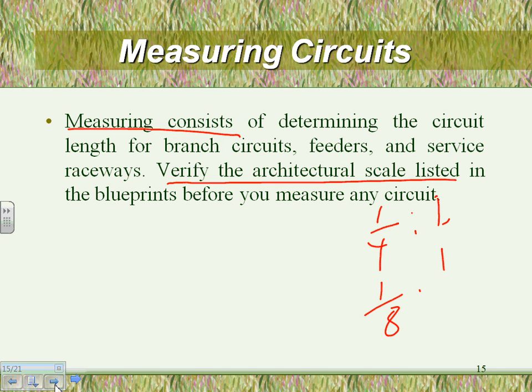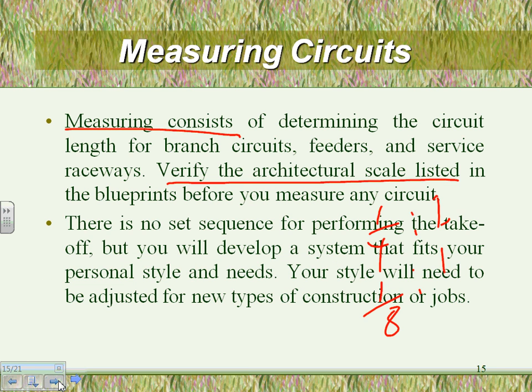A door, like a 3-foot door, or a window, sometimes they have dimensions and certain things to scale. You measure it: it says 4 feet in this direction, and you go measure it. Yeah, it says 4 feet, so the scale is correct. Because a lot of engineers have scale stuff. Sometimes they give you a half scale copy of it, and that will screw up your measurement, especially for distances. For the counts, no problem, but the problem is for distances.